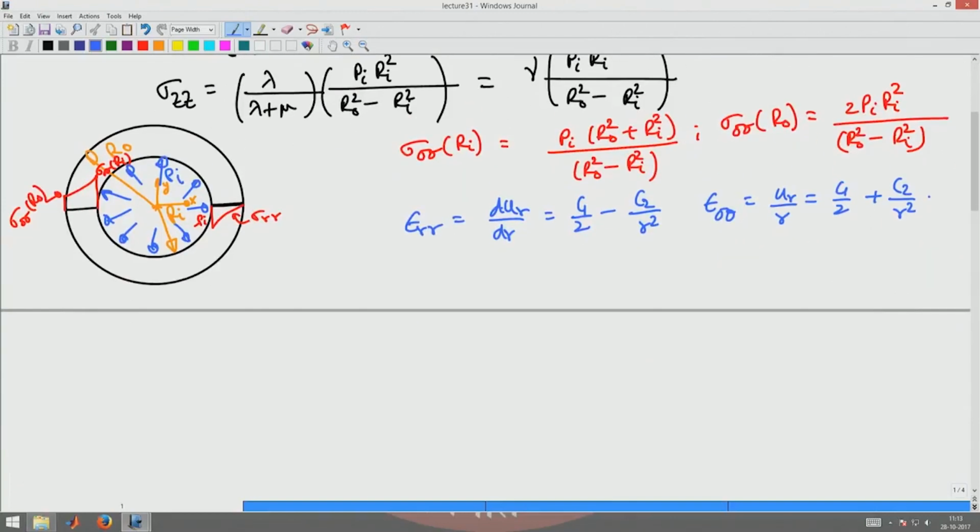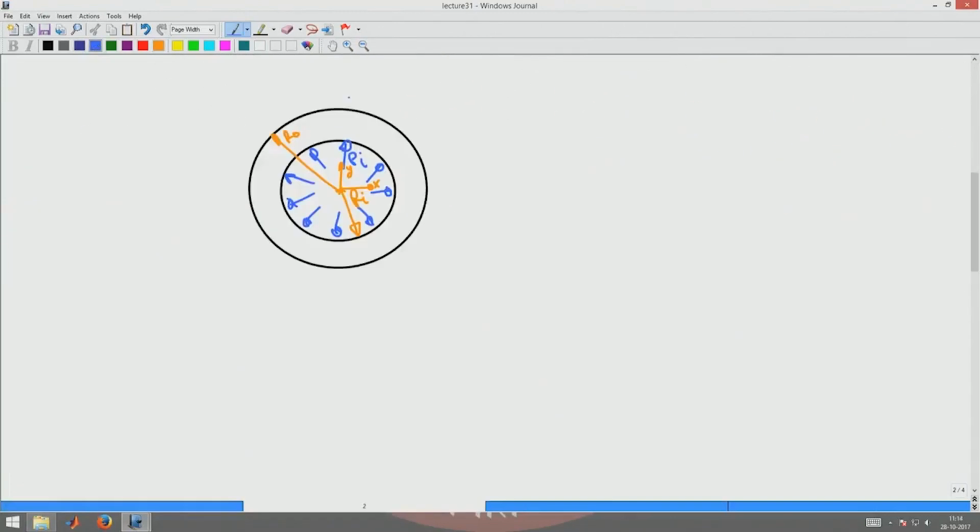The first thing is, say I pressurize it both from inside and outside. I am not going to solve this entire problem, but just indicate how to go about solving it. It is pressurized from outside by a pressure P E, say. Now, this pressure is again opposite to the outward drawn normal to that surface, so this is a negative pressure.